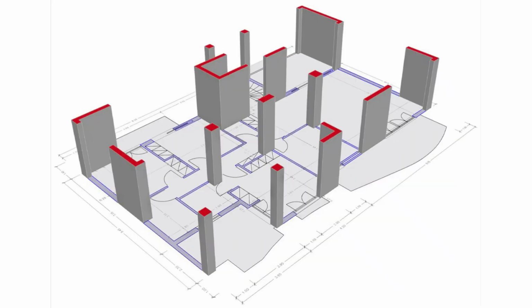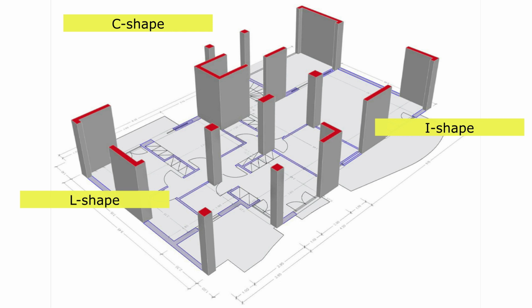The shape and plan position of the shear wall influences the behavior of the structure considerably. The walls are usually in C, I or L shapes, interconnected with coupling beams. Structurally, the best position for the shear walls is in the center of each half of the building. Arrangement 1 and 2 are some good example locations for shear walls.